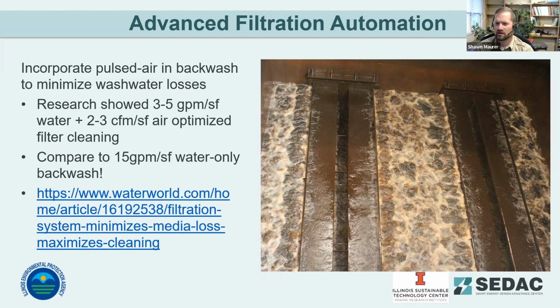And this has been growing across the wastewater industry. There are retrofits for existing filtration systems or brand new filtration systems that can incorporate this kind of pulsed air technology. But again, you're reducing how much of that finished water you're using as your backwash water. So you're reducing how much you have to repump back into your distribution network. And you have some significant energy savings there on the pumping side, and then cost savings on that finished water production.